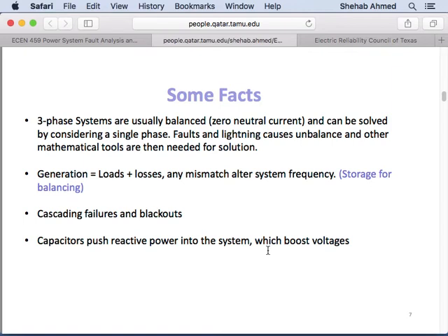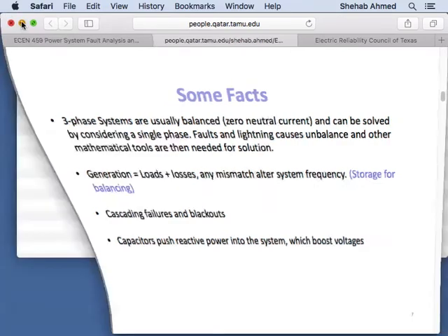You have to generate because this guy has a load. If you're generating extra, the frequency goes up. You cannot allow that to happen, right? So there are some power stations that will be, for example, supplying a base load. Other power stations are on demand to provide peak loads. So it's a good point to talk now about these power stations.